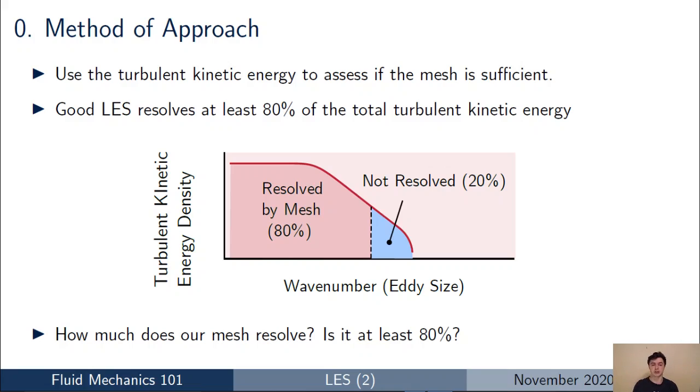So we're going to propose a method for looking at the mesh and seeing whether it resolves at least 80% of the turbulent kinetic energy. If it doesn't, then we're going to have to go back to the mesh and refine it.